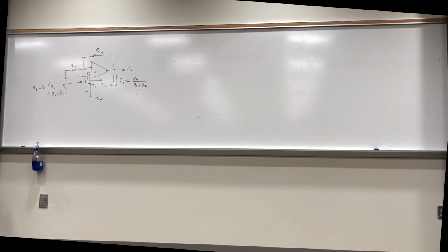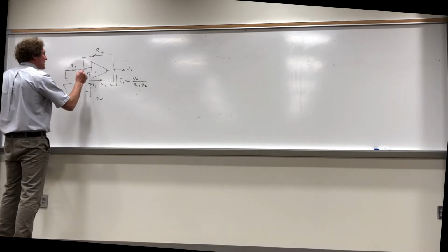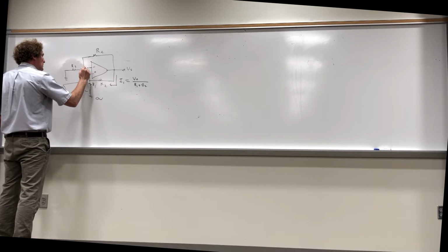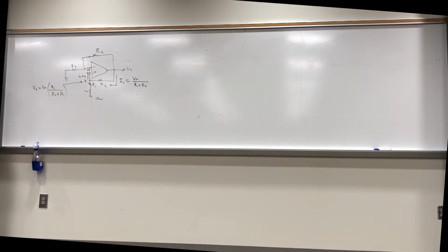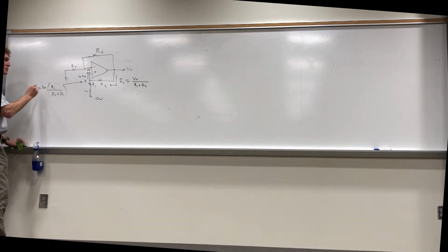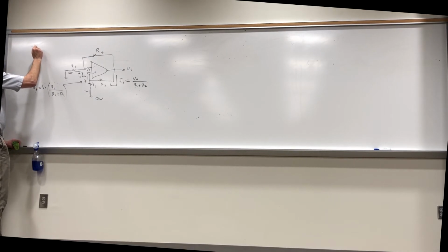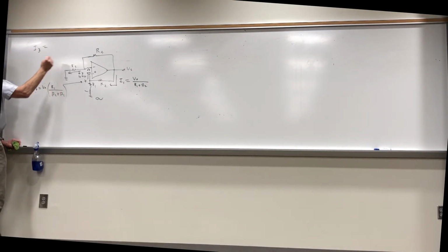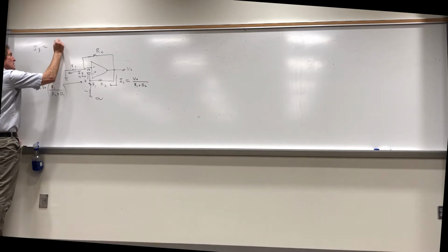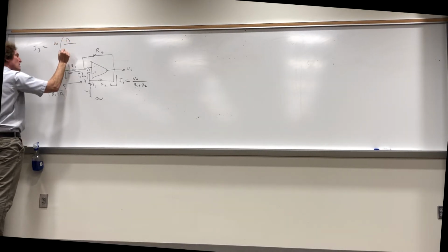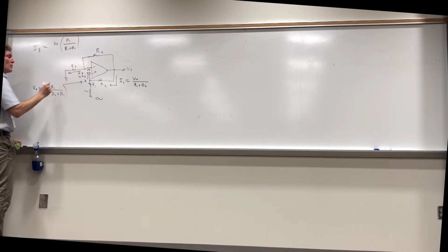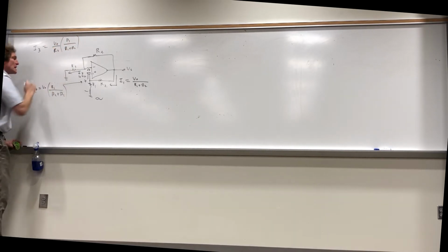All right, what's the voltage on the negative terminal? The same. So the voltage here is the same, and I'll just call it V plus, right? Now say again, are you with me? Keep watching. Remember, I didn't put any values there. Now, if I know this is V plus, which is this, what is the current flowing here? I'll call it I3. It would be this voltage divided by R3, right? V out times R1 over R1 plus R2, over R3. And that's that current, correct?